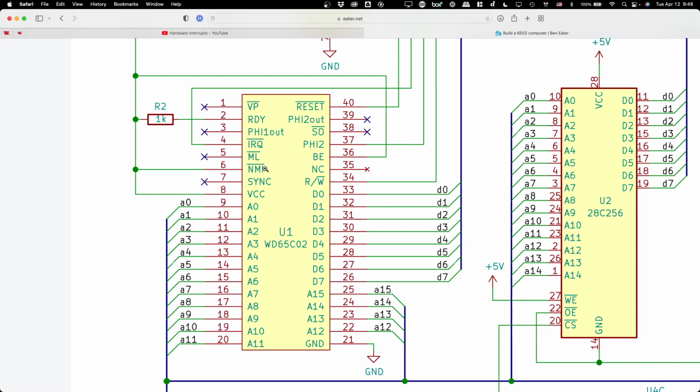Okay, so under what conditions do we want to trigger an interrupt? And really, what is an interrupt, broadly speaking? If we've got a program that's doing a bunch of stuff, an interrupt is a situation in which whatever the program is currently doing needs to stop temporarily so that we can deal with something that's of a higher priority, deal with it, and then return to wherever we were in program execution and continue working.